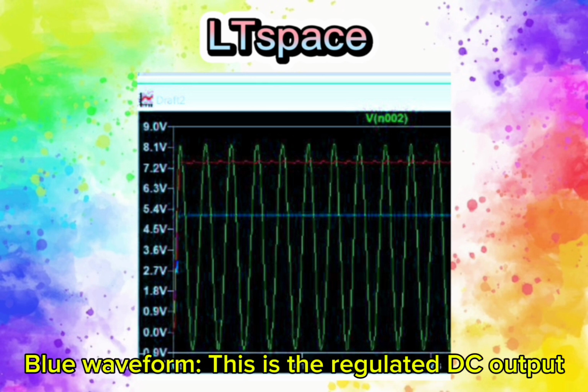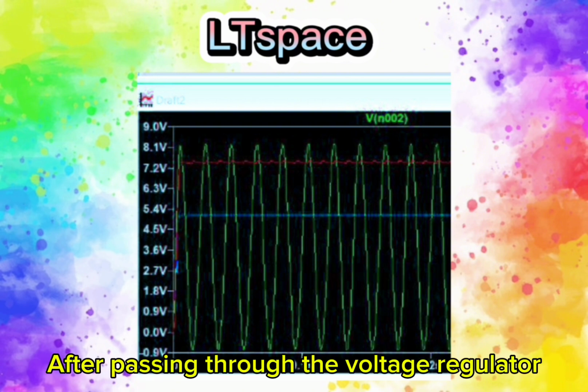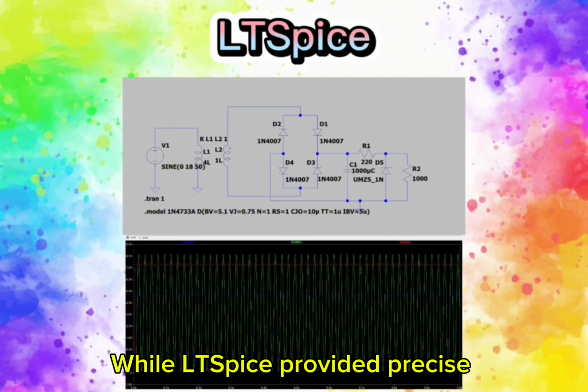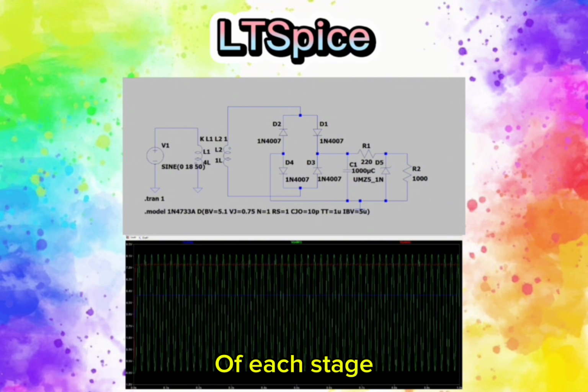Blue waveform: this is the regulated DC output, showing a much more stable and constant voltage after passing through the voltage regulator. By comparing the two simulation platforms, Tinkercad helps us verify circuit logic and connectivity, while LTSpice provides a precise waveform analysis to evaluate the performance of each stage.